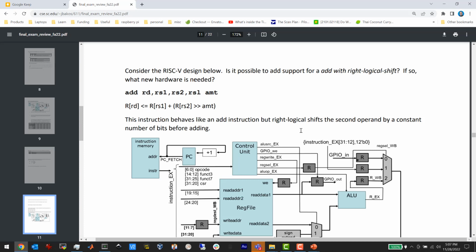Right, unless you changed the structure of the pipeline and you added a delay, added another execute stage or something like that, and made it multi-cycle. Actually, if you wanted to do it with one ALU, you'd have to have 2 cycles to execute that instruction. Make sense? Okay.